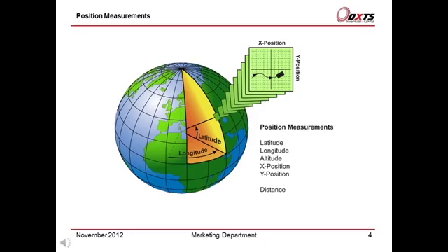To use the local grid, geoidal constant gravity surface, the latitude and longitude of the origin, or X equals 0 or Y equals 0, needs to be entered into the RT configuration software. Then the X and Y position measurements are output on the canvas.